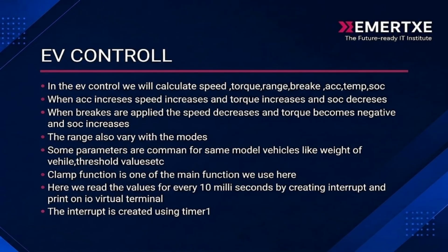Clamp function is one of the main functions we use here. Here we read the values every 10 milliseconds by creating an interrupt and print them on the IO virtual terminal. The interrupt is created using timer 1.